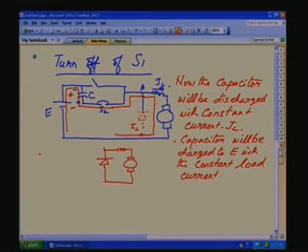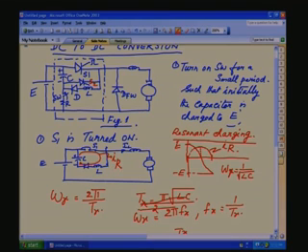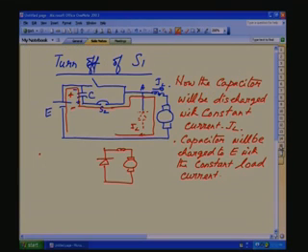What happened to the capacitor voltage at this point? The capacitor voltage again charged in the opposite direction. Now, you do not require the initial turn-on circuit to charge the capacitor, that is this switch SW and R are not required. Now, the capacitor reset will take care of it. How? If you see here, because of this load current, how will the capacitor condition be?